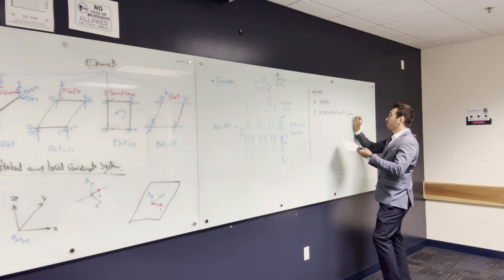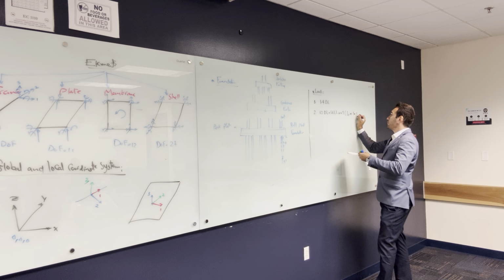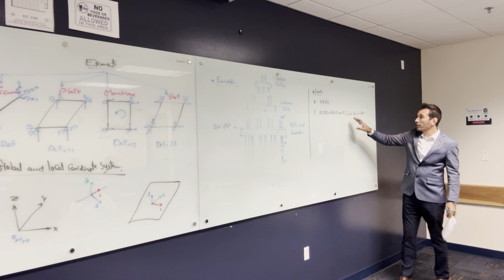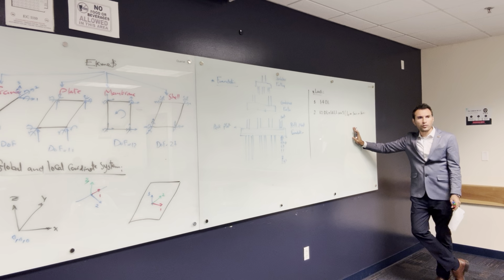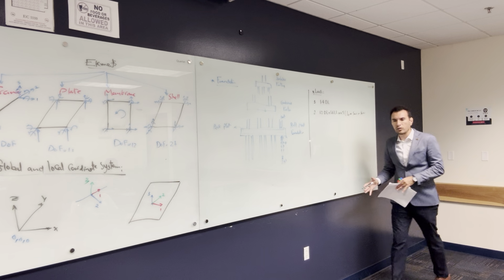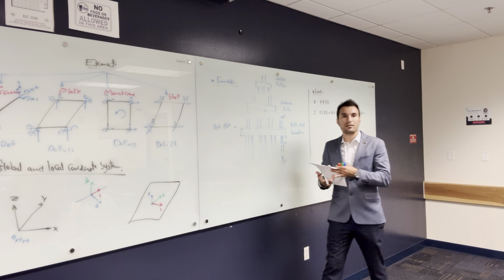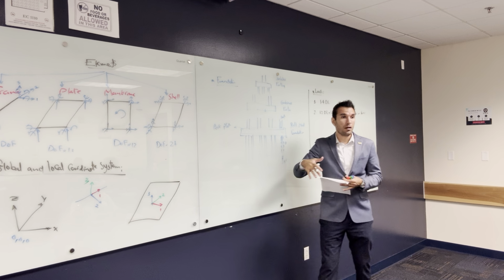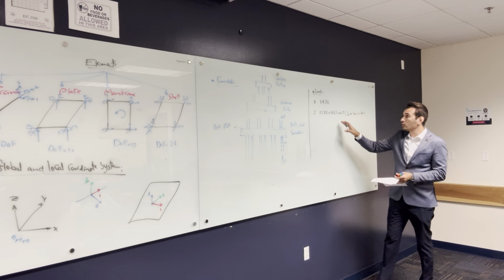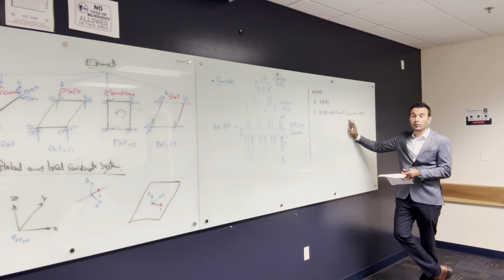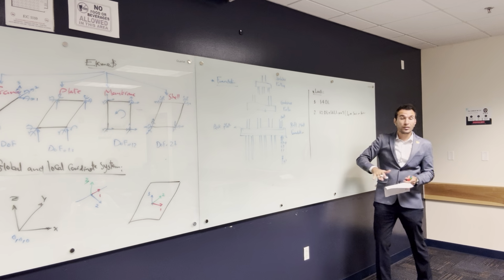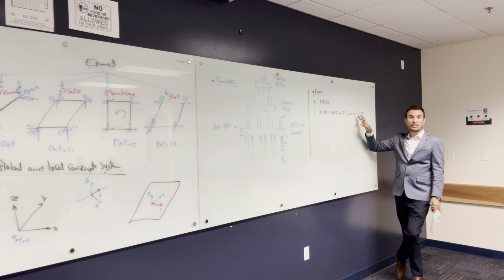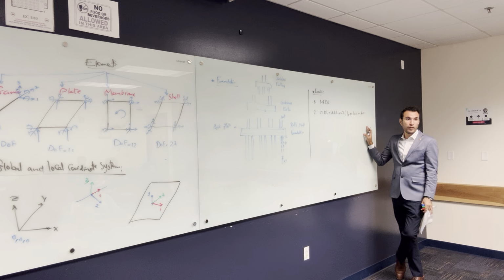This roof load can include live load on the roof, or snow. Here in Florida we don't design for snow, but we can definitely design for rain. What is the roof live load? The roof is a little bit special because it has insulation, sound resistance, and equipment, whatever the structure you are designing for. So sometimes they have a special roof live load. We calculate the live load of the structure separately from the roof live load, because it can be mechanical, snow, rain, or multiple things.